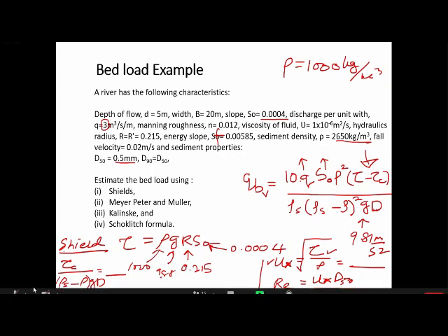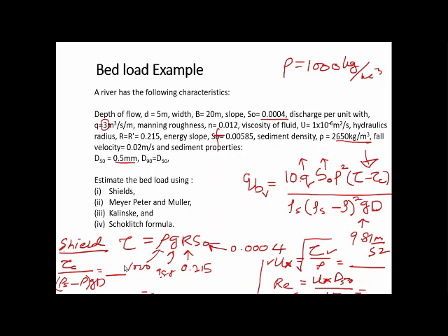So in the earlier question, it requests you to find the Strickler roughness K, and also the K prime roughness that is due to the sediment and bed form. The question does not tell you whether the bed has no bed form or strong bed form. Then you have to fully utilize the equations given to determine K and K prime. If it is given, it is easy. You do not need to calculate. You can just take it as either 1 or 0.5.